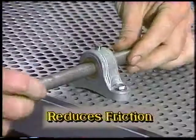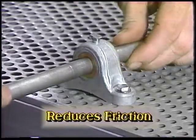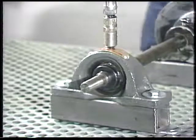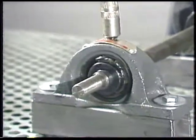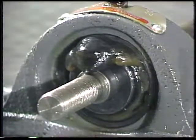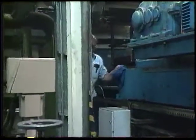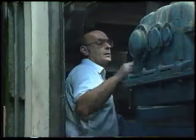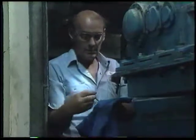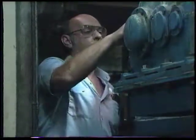With a plain bearing, inadequate lubrication may allow metal-to-metal contact, producing friction and high temperatures. In a rolling element bearing, heat can mean that the bearing is completely dry, or it can mean the bearing is over-lubricated. Excess oil will churn, and its temperature will rise. In some systems, the lubricant is circulated to remove heat. If the oil seems to be at the right level, but operating temperatures are higher than normal, check to see if the oil is actually circulating. A blocked breather hole can sometimes result in false readings of the oil level.